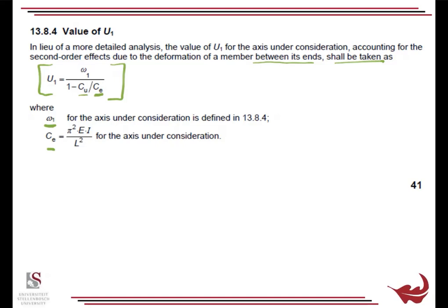So as we get closer and closer to the buckling load of the column, the influence of buckling becomes much greater. The strength decreases as the compressive load increases. So buckling becomes a big deal. And as buckling increases, the deformations between ends increase.